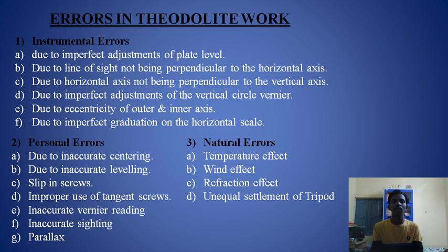Now the next one is slip in screws. If we are rotating the foot screws in the wrong manner, then that will be a personal error. We have to rotate the foot screws either inwards or outwards. If we are rotating both foot screws in the same direction, then that will be an error.